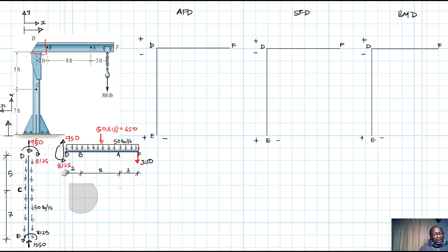So now once we've done that, quickly let's start drawing, using the equations that we're going to use. For the axial force, the change of axial force with respect to y, along that y, is just equal to q, and therefore the axial force itself will just be equal to the integral under the loading diagram dy.